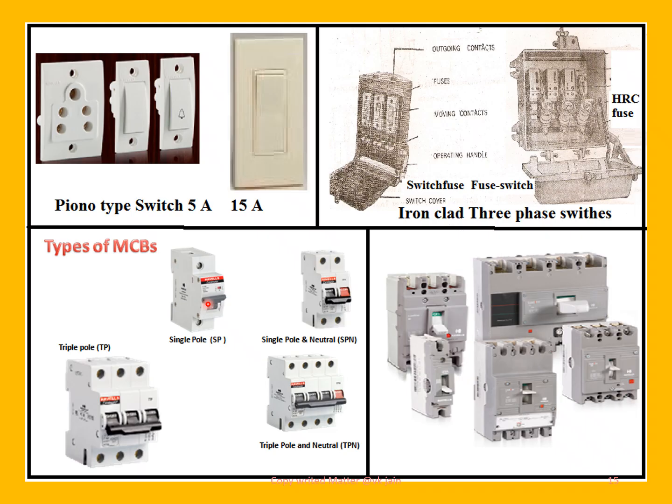So if the load goes to 125%, this will trip. But in case of short circuit, once again it will get tripped. The only care taken is that you can break the circuit, but you cannot make the circuit. For making a circuit automatically, you have to employ some different scheme.